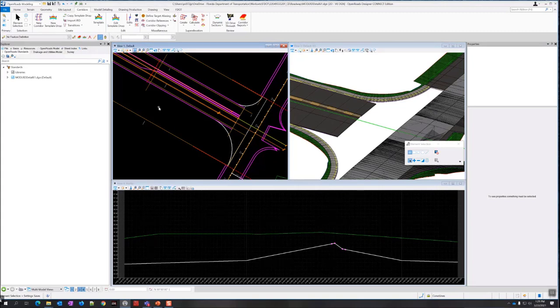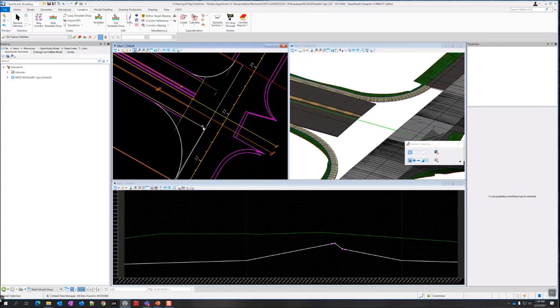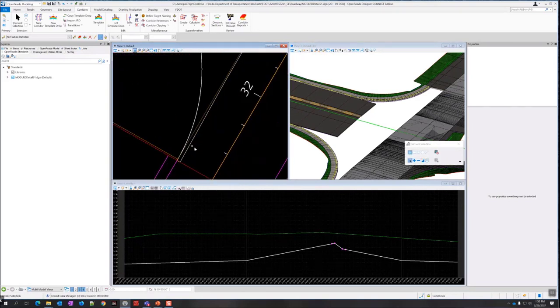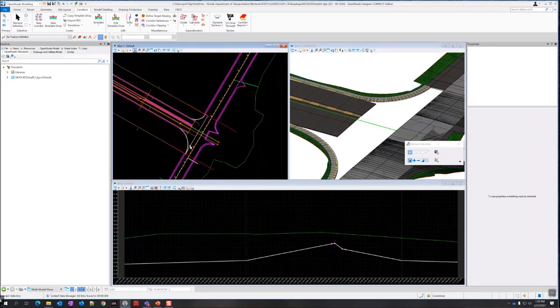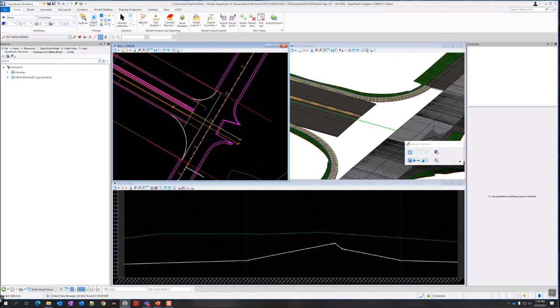All right, so we need to create the terrain now. We have all the elements that we need to do that. Let me just make sure I can select the boundaries okay. So I'm going to turn these corridor handles from the mainline back off, and also the corridor handle probably for the US 98. Let me see. Now I can see that one okay. Actually, I think the US 98 display is turned off right now in the 2D view. So let me just get that ready.